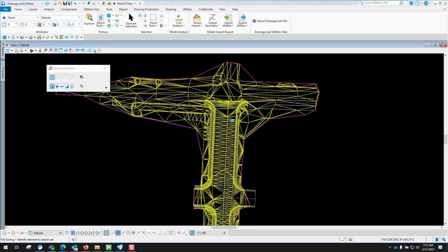Then we will go through and connect those with conduits or pipes between each one of those nodes. Then we will go over placing the catchments that will go into those inlets. And we can utilize those land use areas, that way we can compute a composite C value from those for how much water is going into those inlets. So that's what we will be going over in this part 1 video.